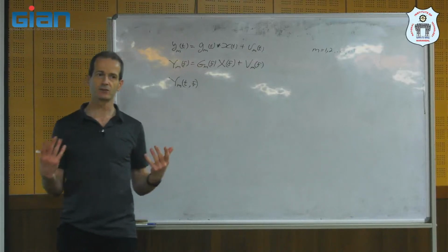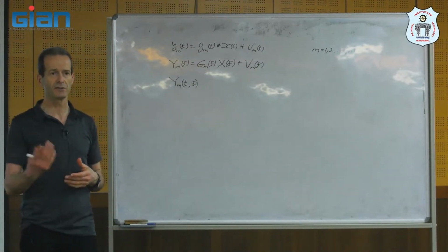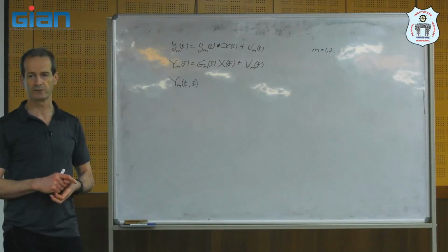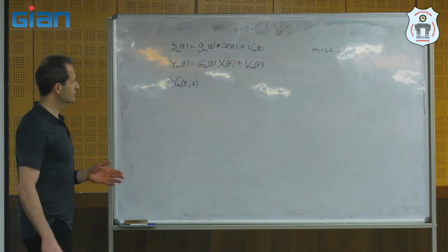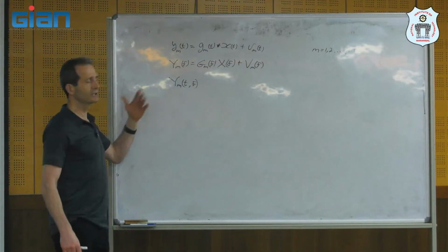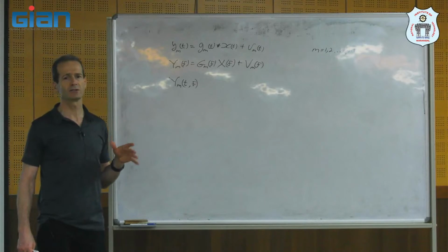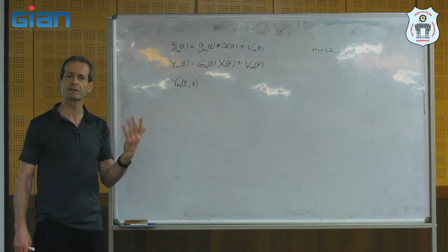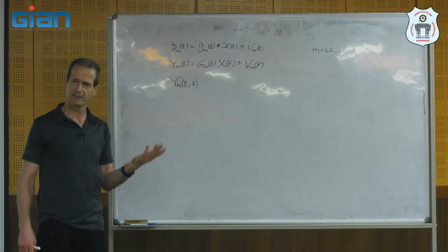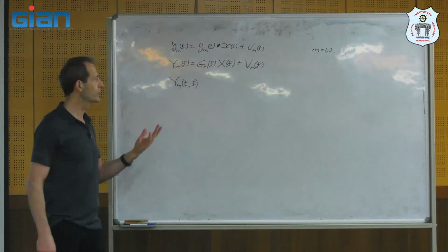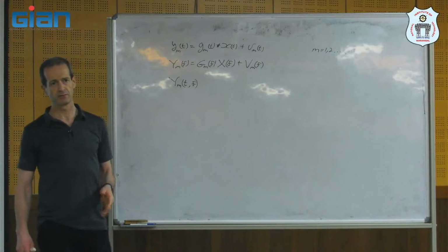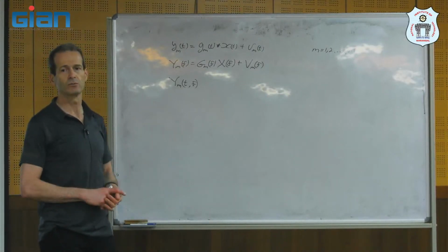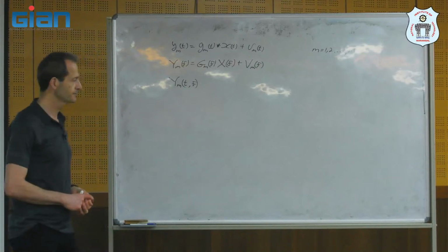That's why we don't work in the frequency domain. We work in the short-time Fourier transform domain, or other transforms related to window transforms. The short-time Fourier transform is very useful because for each window we can choose the length of the window, and it approximates. Instead of working with joint diagonalization, we work with STFT, which is a good approximation depending on what type of signals you have, okay?